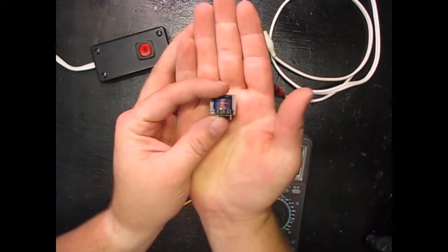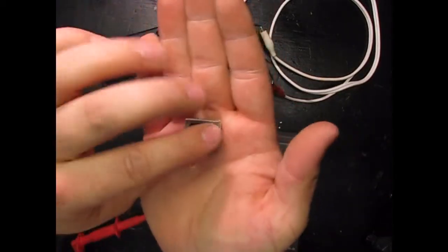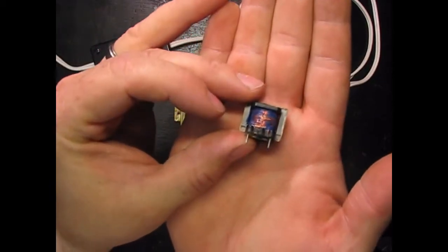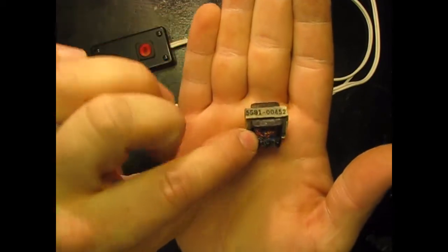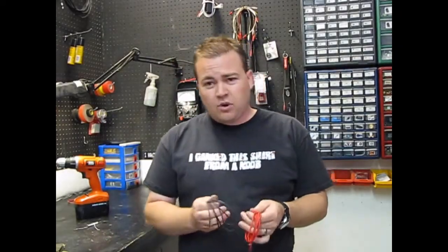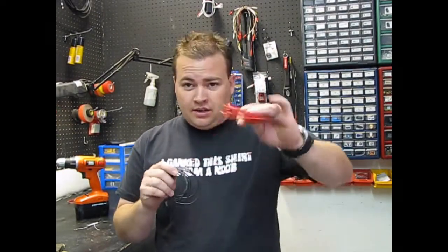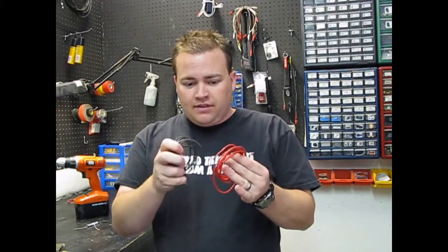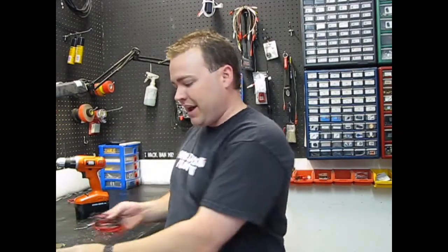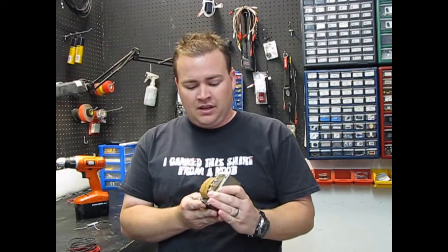Here's an example of a little transformer. It had some blue tape that I kind of scraped off, but you can see that it's basically just wire wrapped around and around. So a transformer in its pure form is basically 2 coils of wire. There's a primary coil and a secondary coil of wire that are not conducting, but they're coiled up and set next to each other in a nice tidy package like this.